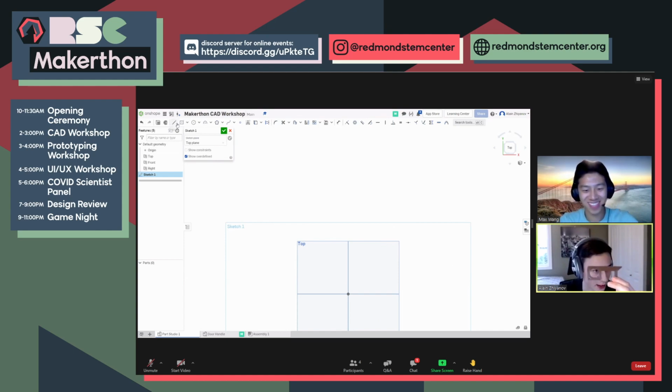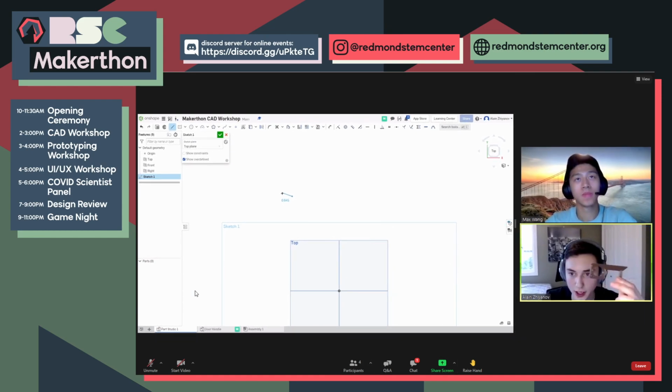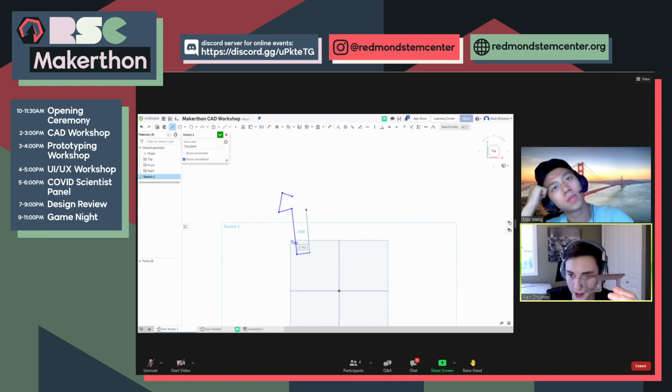So I'm going to create that leftmost L. And for now, you see Onshape is kind of auto-correcting me here. There are some constraints. These are very useful, but I'm going to go ahead and ignore them on purpose just to show you how to use constraints. So this L is going to look a little weird for now. Oh, I messed up. One of them's already constrained, but that's okay. And so you can see we have a very rough L shape here.